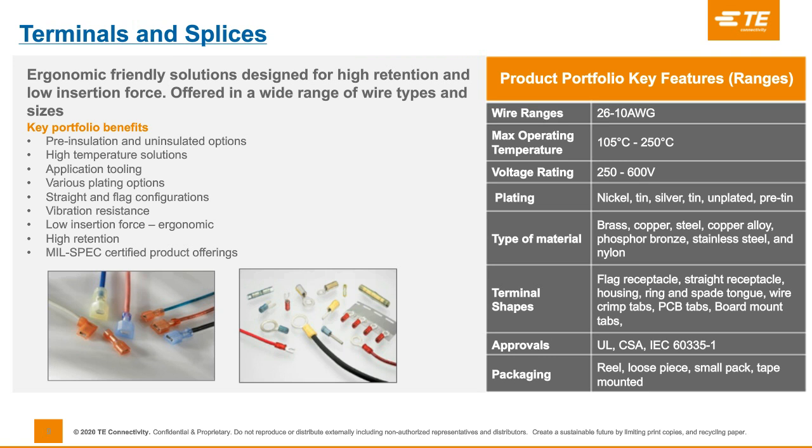I mentioned low insertion force, but also high retention. Although you may have low insertion force, so the amount of force it takes to mate those onto certain tabs and so forth, make sure it does have a high retention so it does not tend to slide off the tabs or demate from their mate due to vibration.